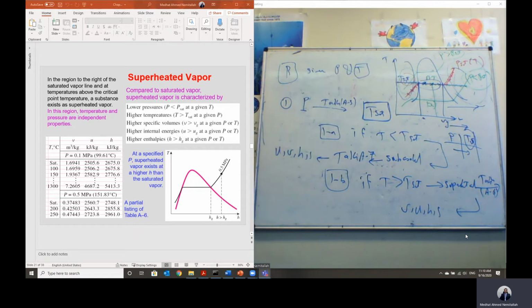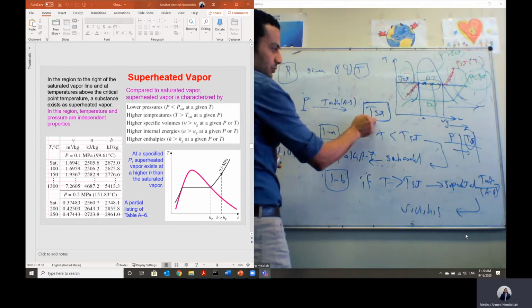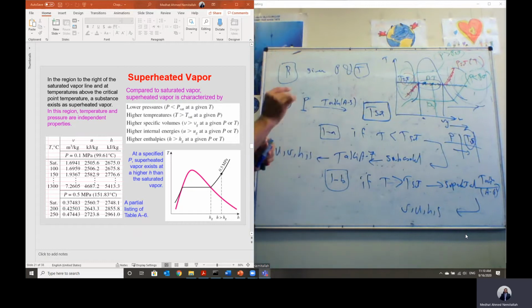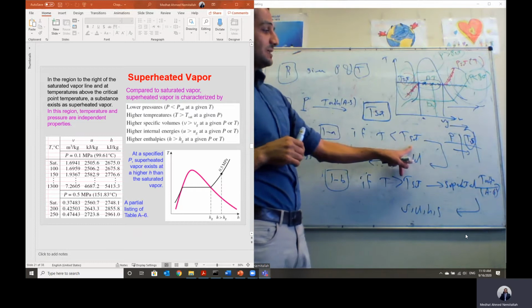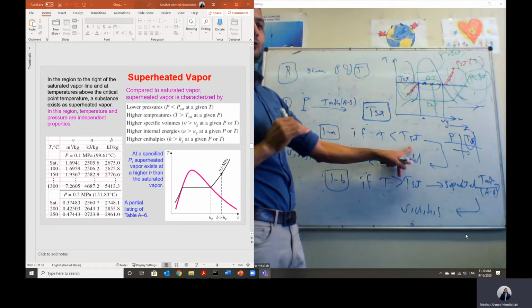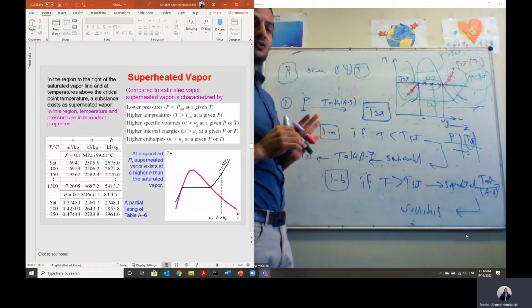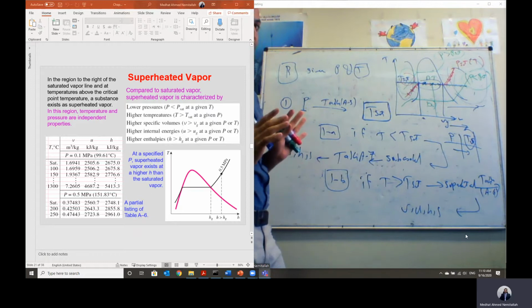with the given pressure. Usually I prefer, if pressure and temperature are given, to take the pressure to get the saturation temperature, because you keep it in mind very well that if the temperature is less than T saturation, then it is subcooled. If it is higher, then it is superheated. But the reverse in case of pressure. But I will write it down as well.